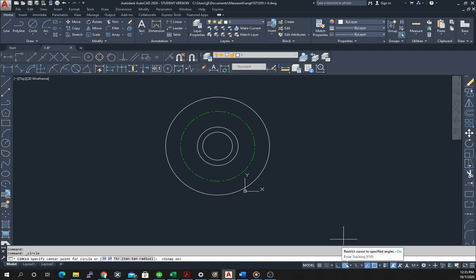And then finally, we want our polar tracking. Without polar tracking, we get some reference lines, but we don't generally get all reference lines. So we sort of get this horizontal line in some cases as we go to pick points, but we're not getting them everywhere.